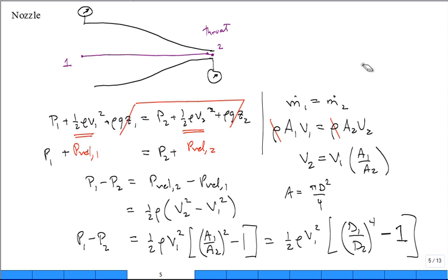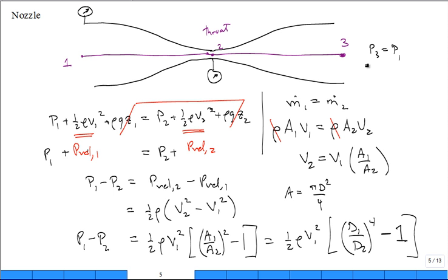That's a nozzle. Guess what you can do to a nozzle? You can put it with a diffuser. If I took that diffuser and I went back out to the same exact area, the same diameter, diameter at 1 is equal to diameter at 3. What are the assumptions of Bernoulli? Inviscid, no frictional loss. What do you think the pressure at 3 is going to be? Pressure at 1, you recovered it. What's the speed at 3 going to be? Back at 1.